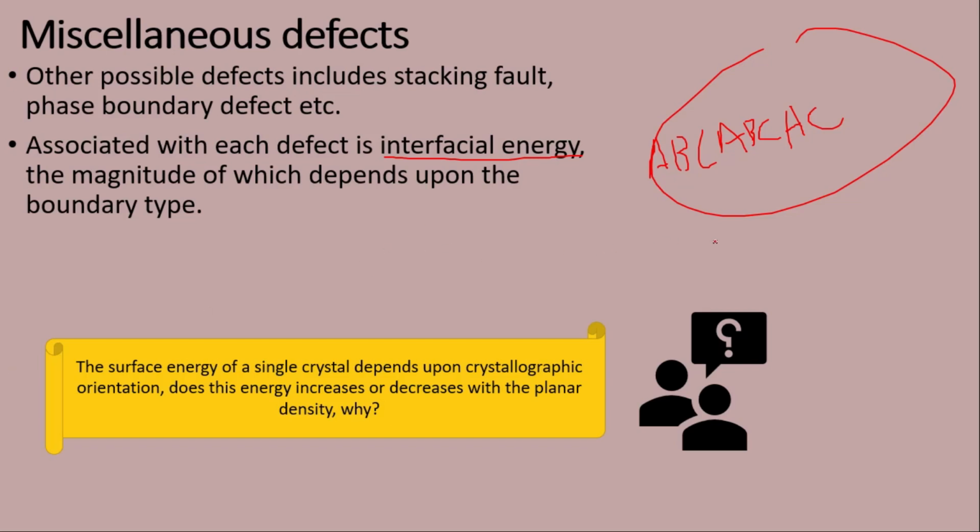So this is the end of this lecture, and we have discussed in this lecture the two major kinds of defect. That was the one-dimensional, the linear defect, which is also called a dislocation. And in dislocation we discussed the phenomenon of slip, which is also a dislocation motion. And we discussed two different kinds of dislocation, either edge or screw dislocation. Then we moved towards the third type of defect, that was the planar defect or two-dimensional defect. And in the planar defect we discussed the external surface defect, that the atoms at the external surface are less bonded, so they more readily react with impurities.